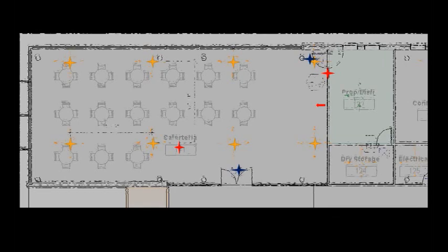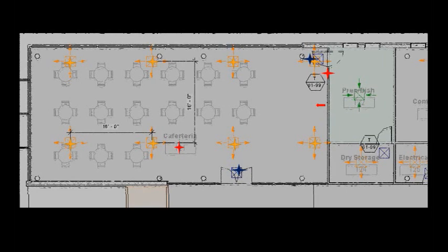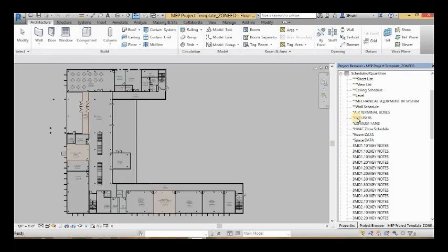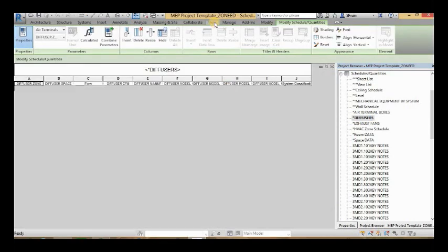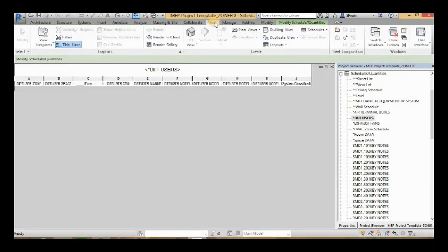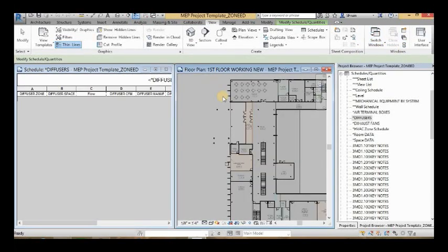So I hope this helps explain. I know we'll get into the script here in a little bit, but this is what the end product will look like. And that's the rules on how we got there. Also, just like we found these door points, those could be windows to help us find something. That could be toilets in a room to put the diffuser right over that. Maybe equipment, whatever. So let's hop into this Revit model.